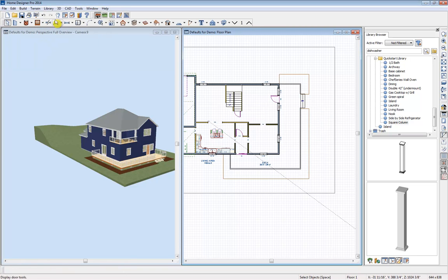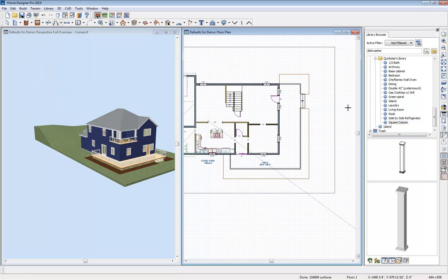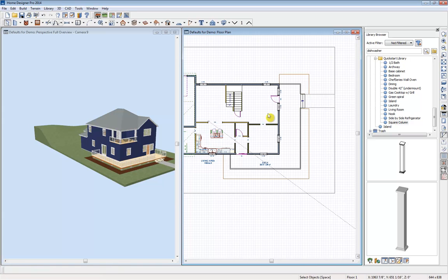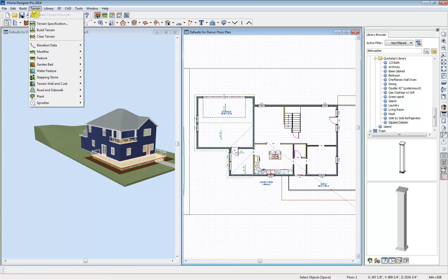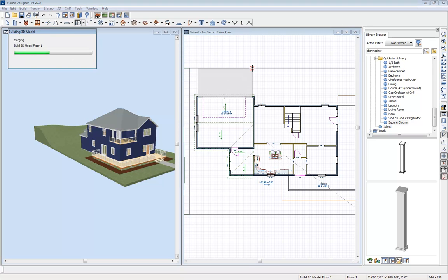And speaking of space to walk, let's put a sidewalk there. So I can drag it out from the stairs to the edge of my terrain, and then I'm going to resize it. Sidewalks resize on either side, but you can change the edit properties. And then I also need a driveway area, so we'll come to our terrain tools again, and we'll do a driveway. And this one we're simply going to drag out just as we did the polyline garden bed.